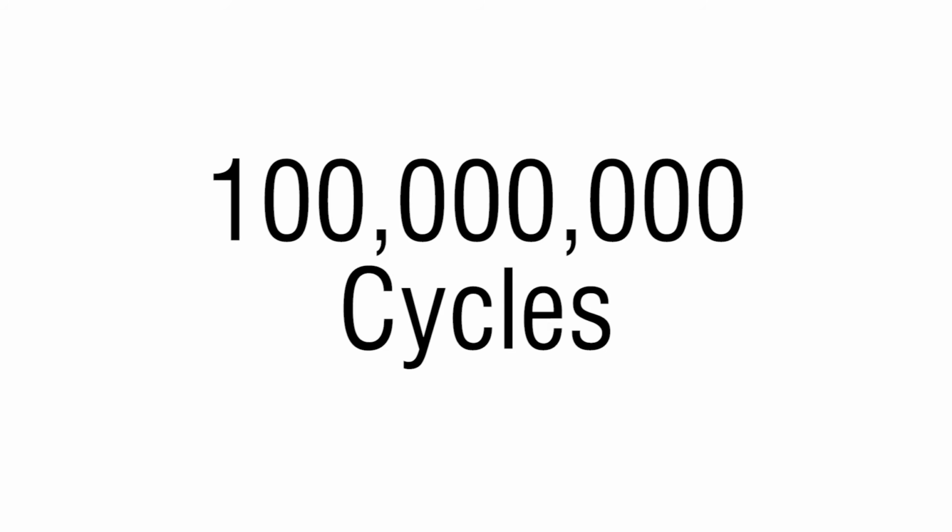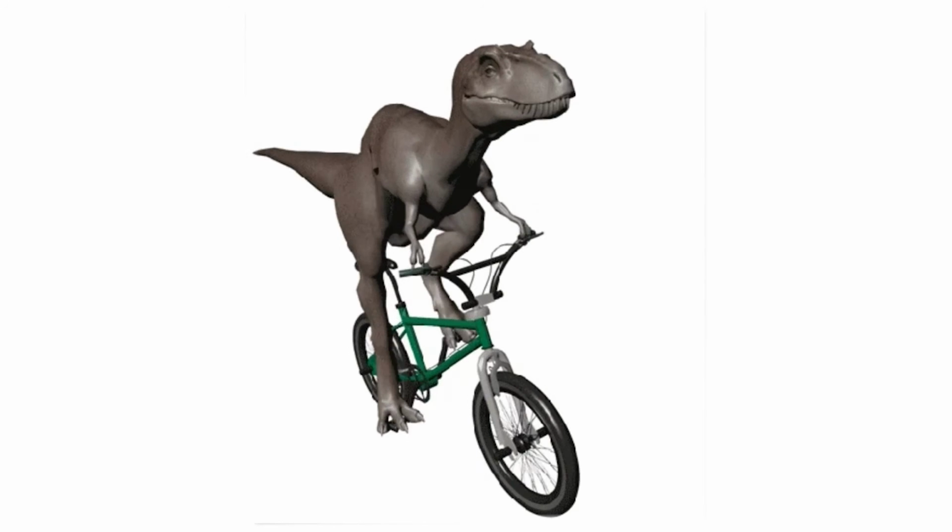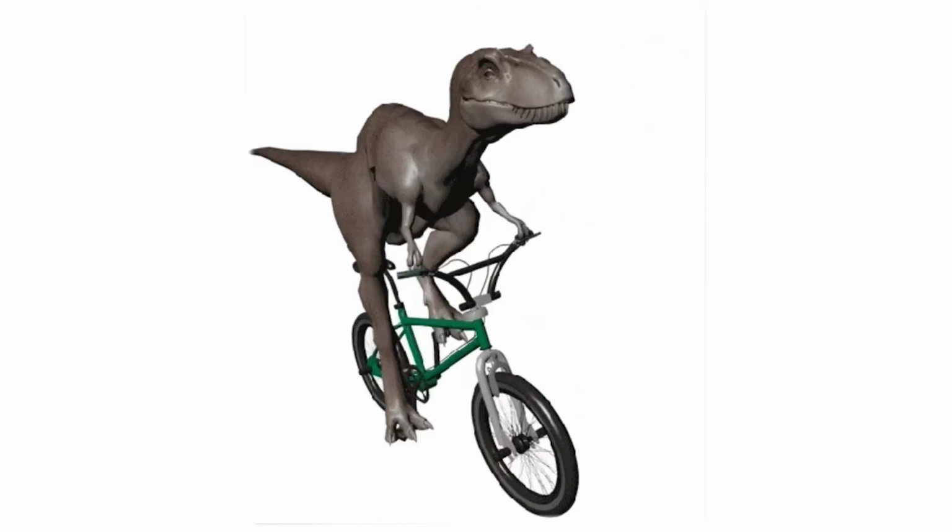This assessment determined that a shock under this specific loading scenario has a lifetime of 100 million cycles, or 273,690 years, roughly 1,348 times longer than bicycles have been used by humans. In other words, fatigue failure in a bicycle shock is of negligible concern.